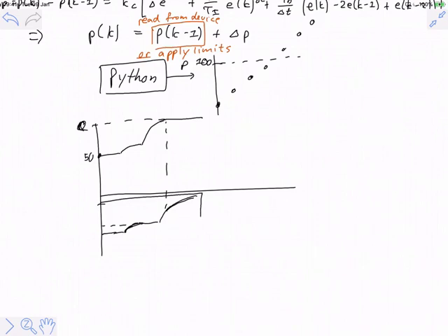And if we then take the set point down, the difference between a position form and a velocity form will be that the velocity form will come away from that limit immediately when the set point goes down, while the position form will continue along and then come down after that, because it'll be wound up and it'll have to unwind to get down. So that is literally the only difference.